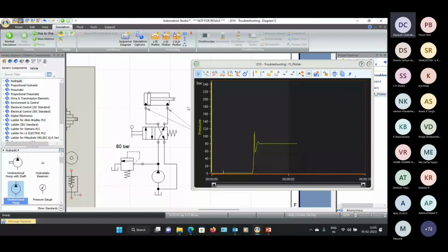That is a full force stop, and at that time the pressure of 80 bar, you see in the graph here, there's a spike when it hits the wall. The cylinder can't move, and the full 80 bar from the pump is hitting the piston. That is when the pressure relief valve trips and starts letting out the extra pressure.